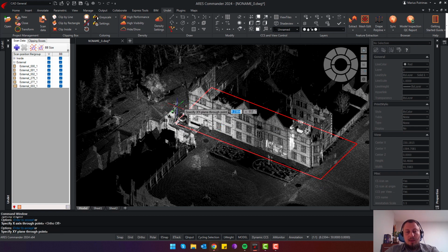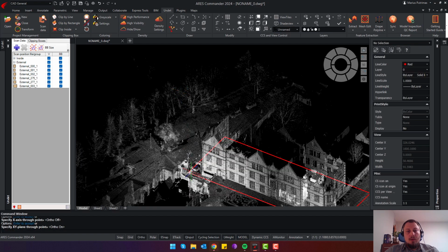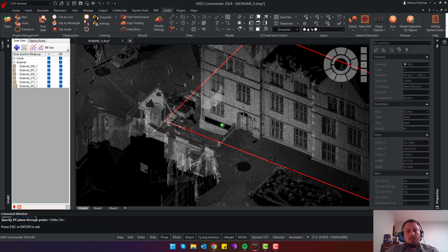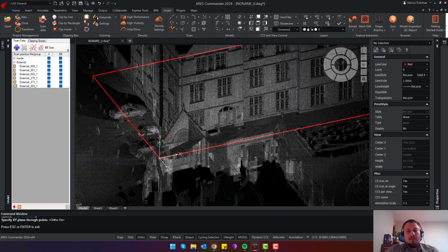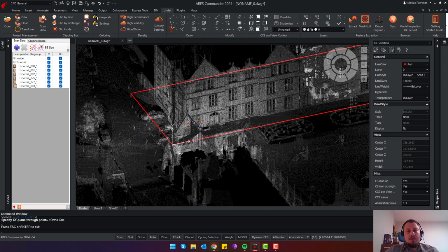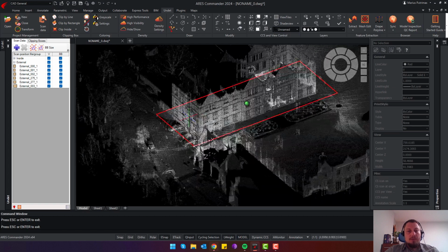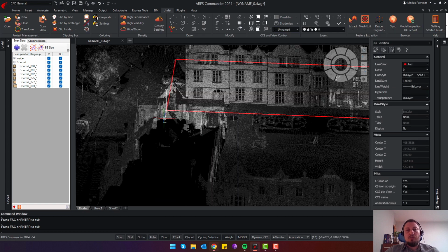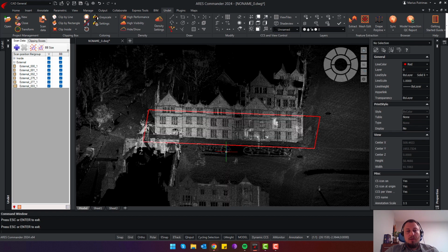We'll activate F8 ortho mode and point my Y-axis to the top. And now, as you can see, the drafting plane axes X and Y are oriented to the building elevation, and the Z axis is looking to us. So it is the correct setup of the elevation.